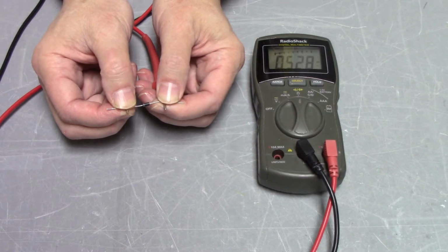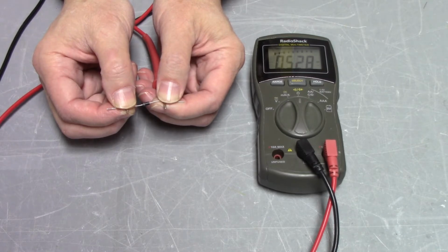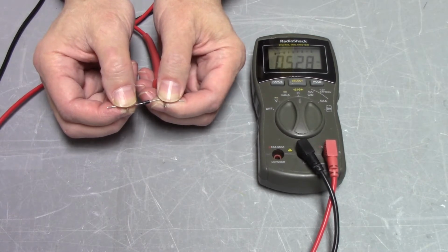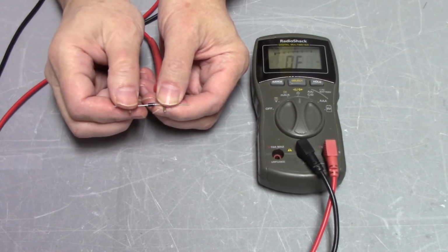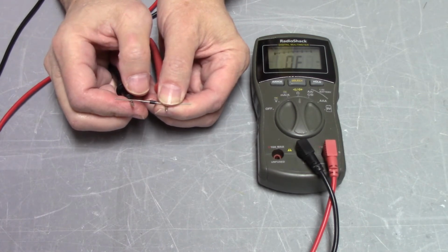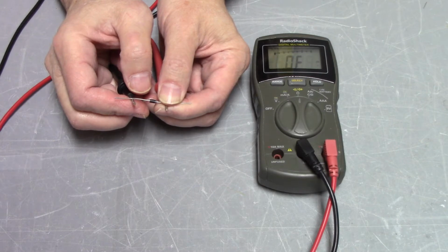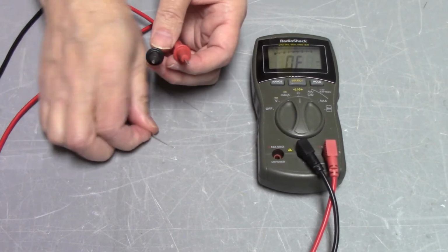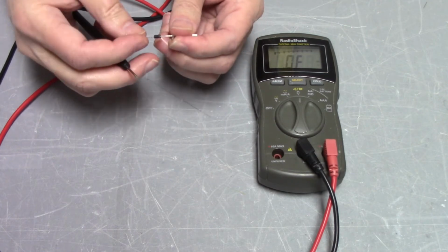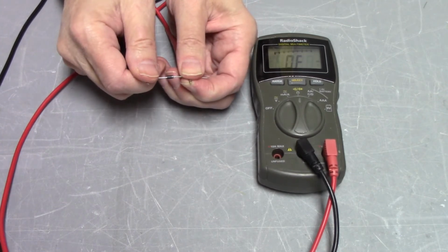Now, what this meter does is it puts a current out of perhaps a milliamp and then shows what the voltage is with that 1 milliamp. And when the diode is forward biased, you get about 0.5, 0.6, 0.7 volts, depending on the diode and how much current. Now, if we flip the diode over, we put it in a non-conducting direction, or reverse bias direction, and what we see is an overrange indication. That says it's an open circuit, the same thing we get when we just do that. The diode in that particular orientation is reverse biased.